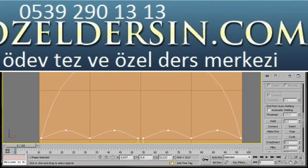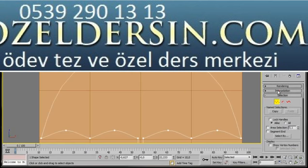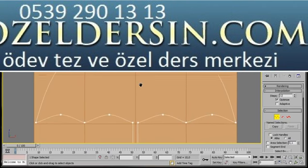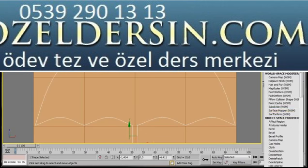But I think the edge looks a little jagged. We can fix that. Let's scroll up here, and we're going to go to interpolation, click on that, and now here in steps, let's just boost our dial up a few, say something like 12. There we are. That's very smooth now. Click on the word line to come out of the subdivision mode, and now we'll go to the modify list.